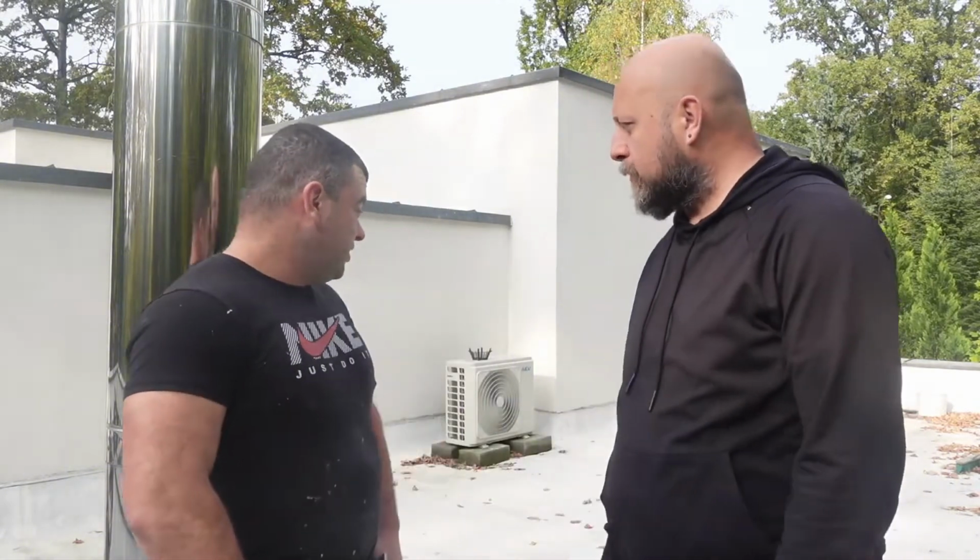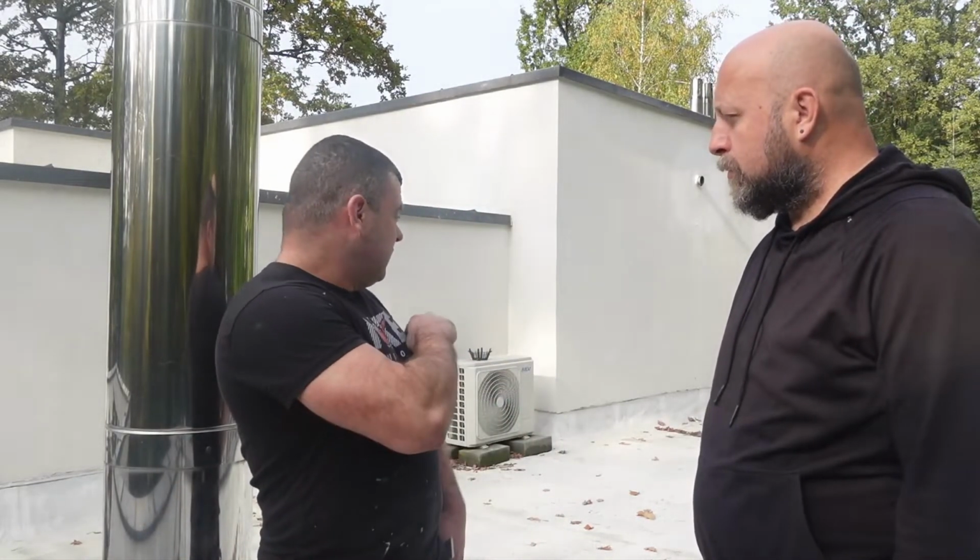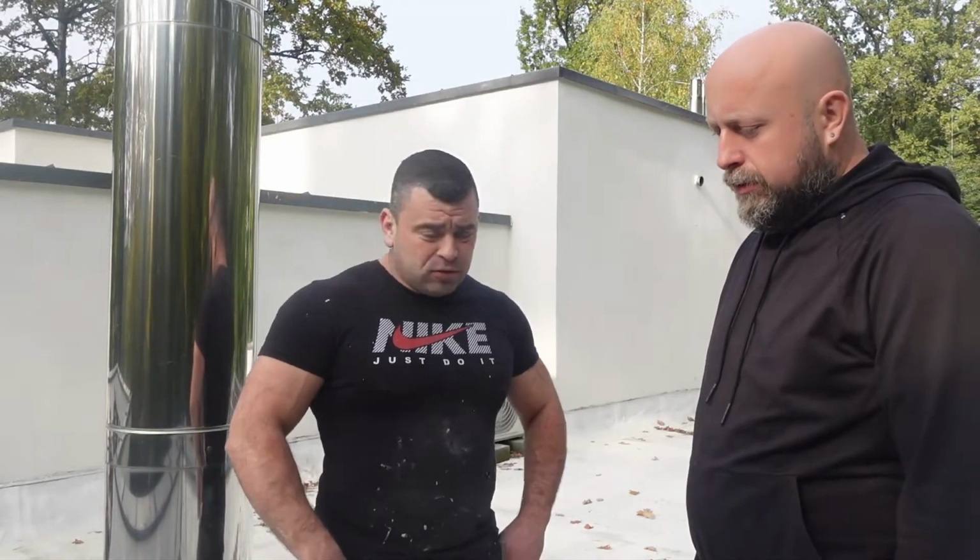In the meantime, we also had to fill some holes because the styrodur was unevenly placed, and we had to simply even out those holes with a special putty so that even after the proper roofing, water wouldn't pool and freeze in winter, creating an ice rink. This is known to have a very adverse effect on the roofing material. Water that stands and freezes, the material underneath expands and so on. Micro cracks form and we have a problem again after some time.